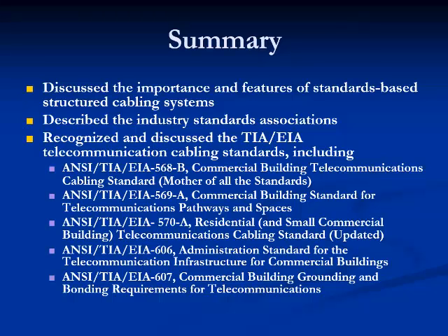569A is the commercial building standard for telecommunications pathways and spaces. 570, which is the residential and small commercial building telecommunication cabling standard. 606, which is the administration standard for telecommunication infrastructure. And 607, which is the commercial building grounding and bonding.